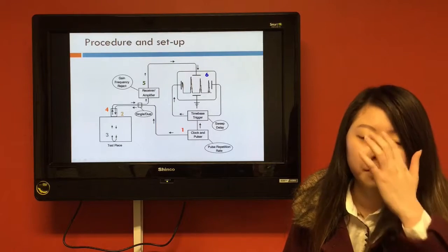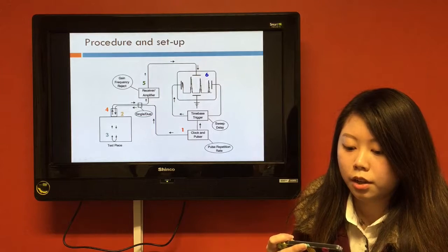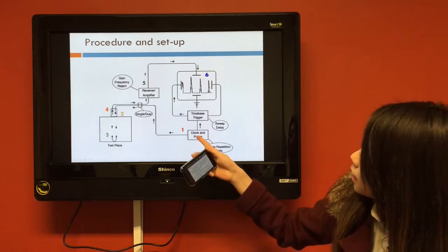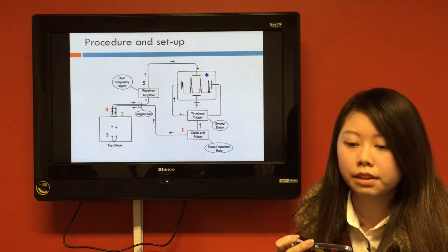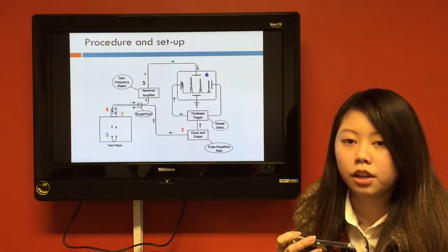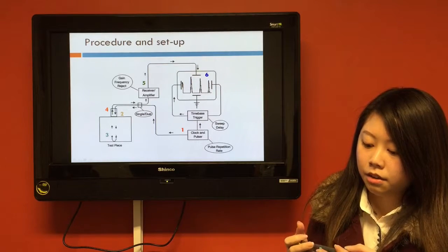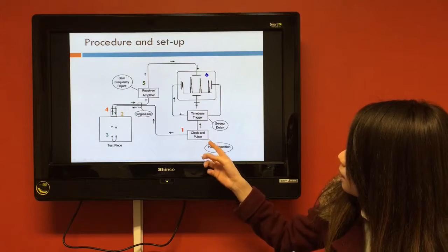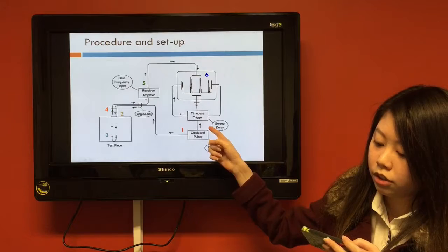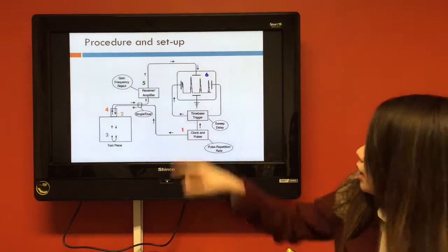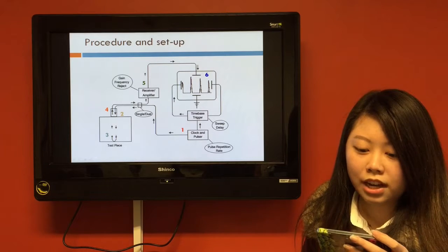Let me introduce the procedure of setting up the ultrasonic system. First, the pulser emits a short high voltage pulse to the transducer after receiving a signal from the clock. At the same time, the pulser will also supply a voltage to the time-base generator module. The time-base generator module starts the spot on the CRT screen, and the voltage pulse will travel